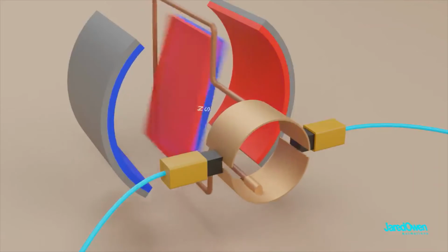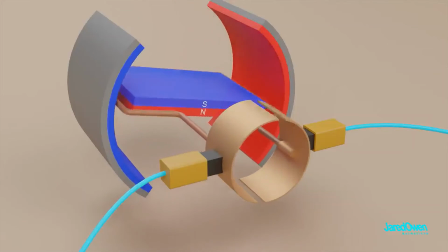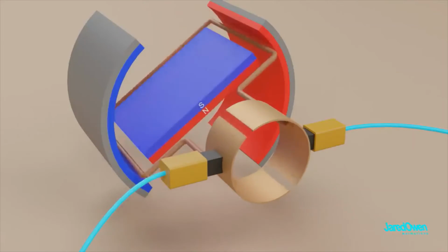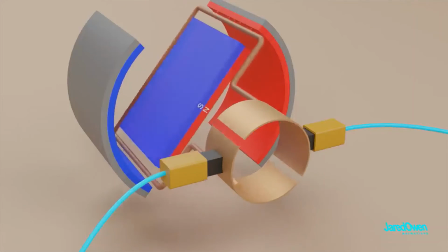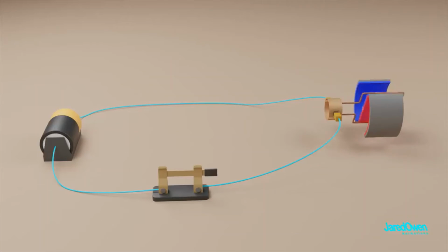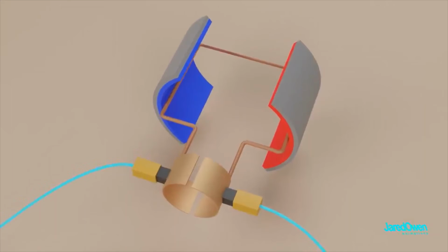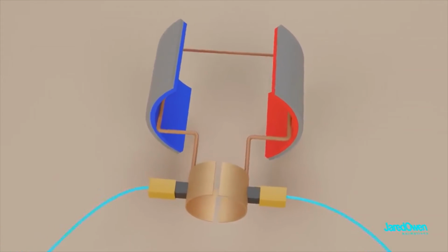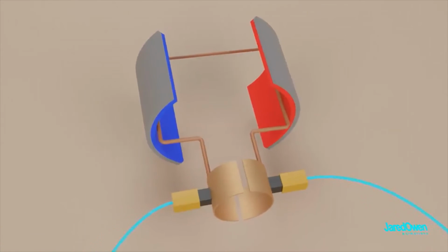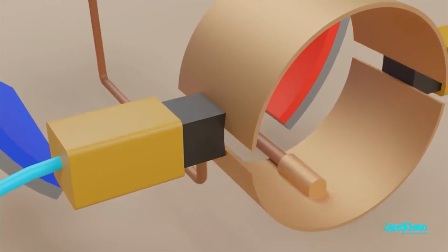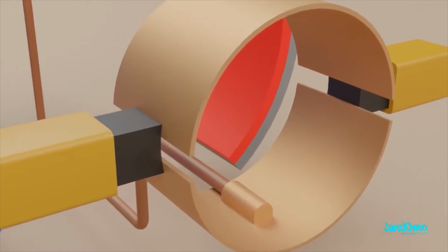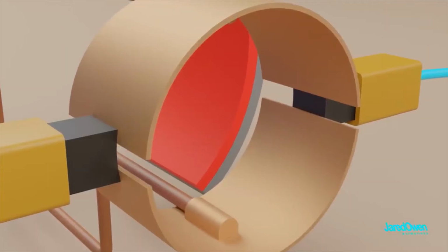This commutator ring does the same thing as switching the wires like we were doing before, but this time it does it all on its own. It will continue to spin as long as we're connected to a battery. Disconnect the battery, no more electromagnet, and the spinning stops. Now so far we've only used one loop on the armature. This will cause our motor to have an irregular speed, and in fact, we could get stuck in this position, with the brushes halfway between commutator segments.